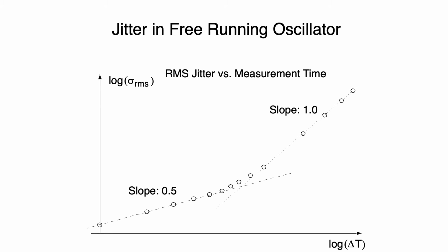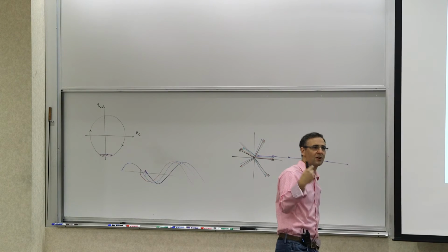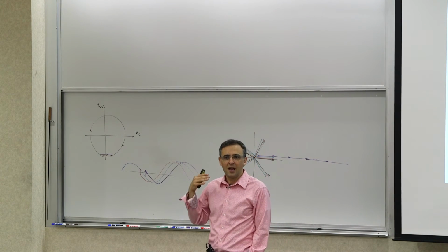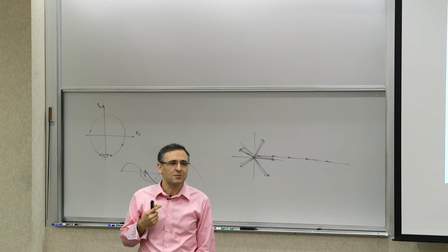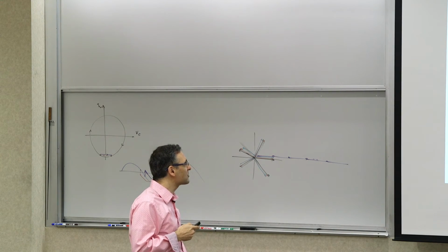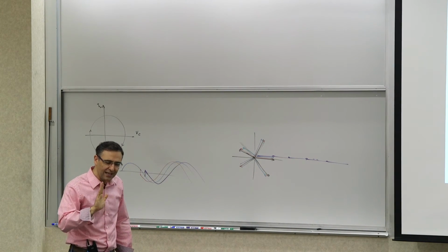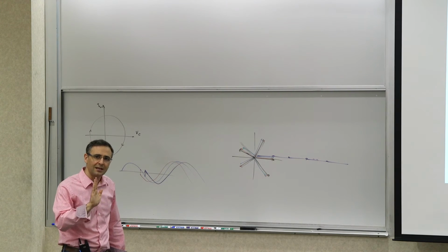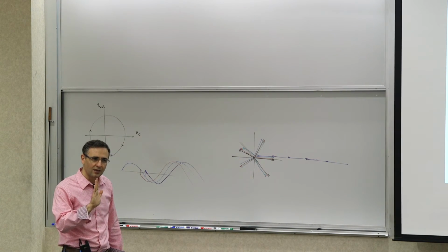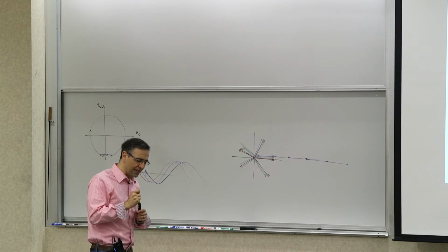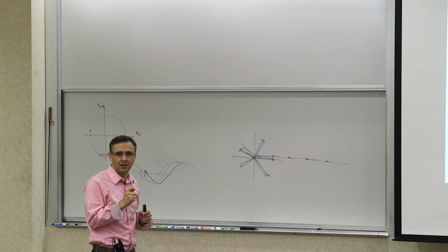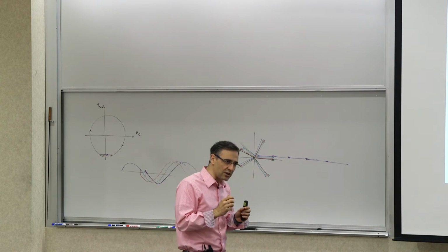So why is that? Why do you get these two regions? We said we will talk about it later. If you think about it, it really goes back to two different things. Now, if you have transition errors, let's say you're thinking about the ring oscillator. During each transition you introduce a little bit of timing inaccuracy, timing jitter. So we go through transition 1, you introduce some jitter, and then you go to the next stage and you introduce some jitter.